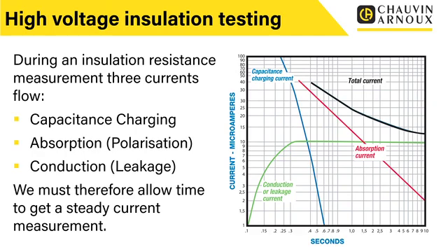But what you will see is that when we first apply the test voltage, we will get a current flow, and that current flow is effectively going to charge up that capacitor. So initially we get a current flow, but once that capacitance is charged up, that current basically goes to 0, or certainly becomes negligible. So you can see there the blue line when we first start off, probably for less than a second, we will see this charging current.